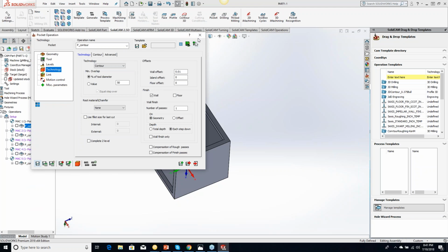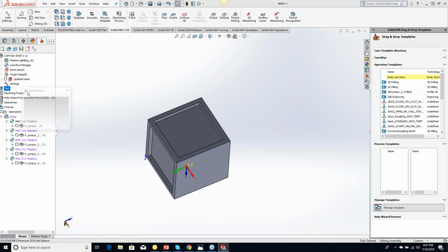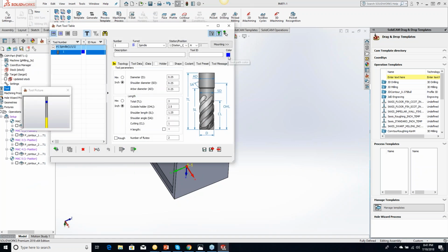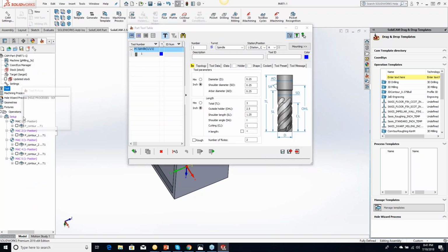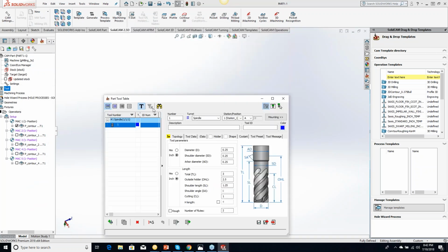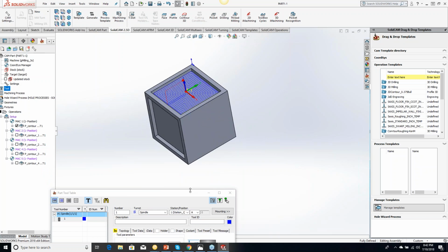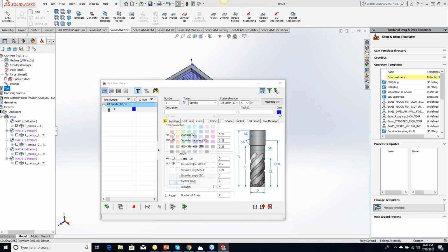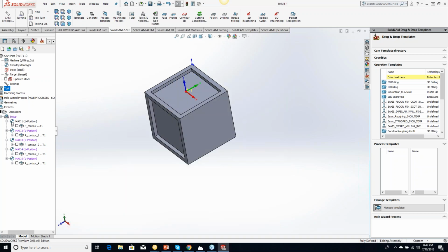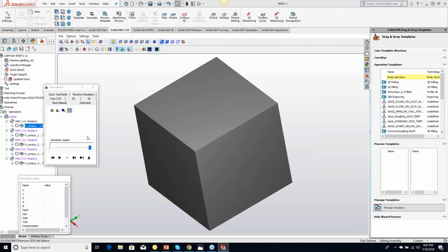And for those of you that are kind of unsure what I'm saying about the color, is that tool, you can actually pick the toolpath color right here. So that's going to, our toolpath is in blue. Let me get this part around. But if you wanted that color and a different color, say yellow, hit OK, save and exit, turn it on, and we have yellow. So, and that also plays through in the solid verify. Instead of showing blue, it'll show yellow.